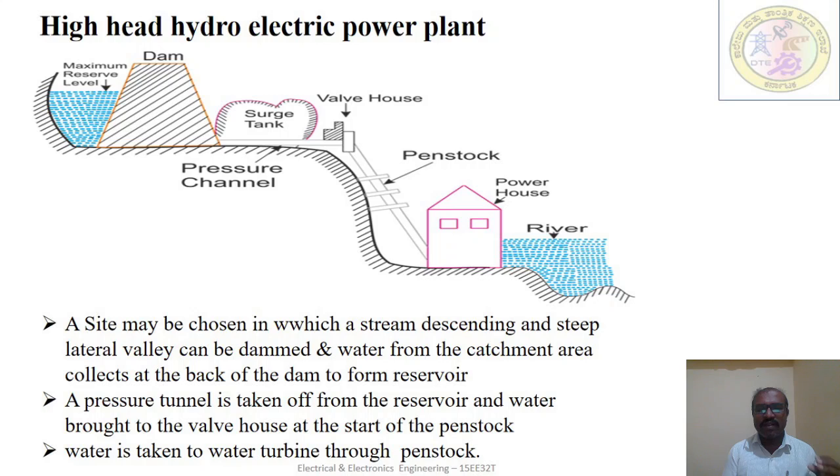The huge amount of water through the penstock, which is falling from a minimum head, will have a high kinetic energy from top to bottom. When the sudden water is stopped in a penstock, the water will move back in the penstock in the reverse direction. That means from the powerhouse back to the surge tank. The surge tank absorbs this pressure swing by increasing the water level, which is thrown back from the turbine house.